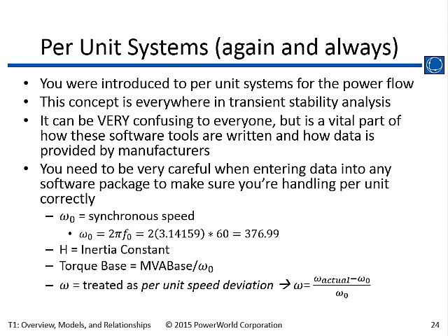We'll talk about this a little bit later on. Frequency values like, particularly, there's one called damping, which is never clear whether it's in per unit or in actual units. We did some work for some utilities in China, and in China everything is on 100 MVA base, including the generator parameters.